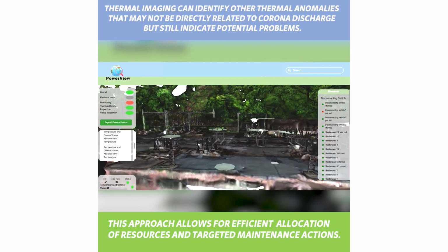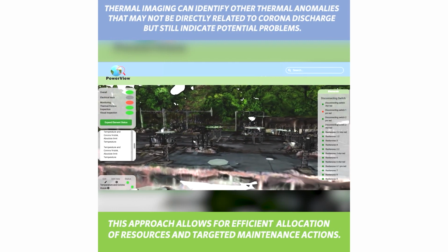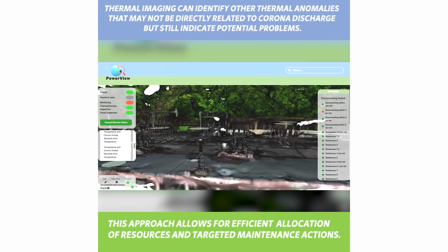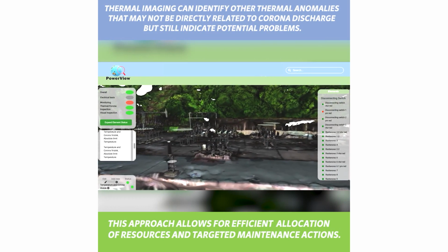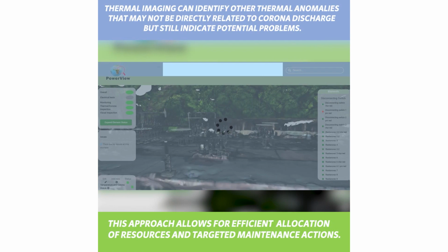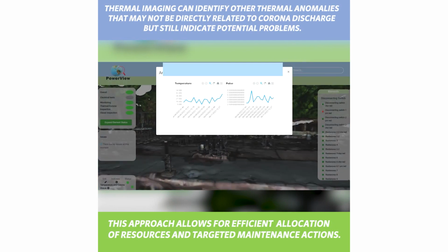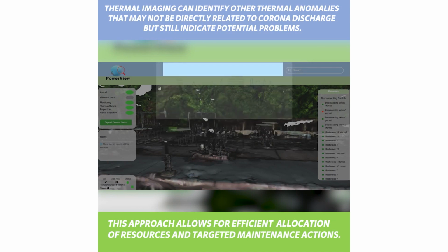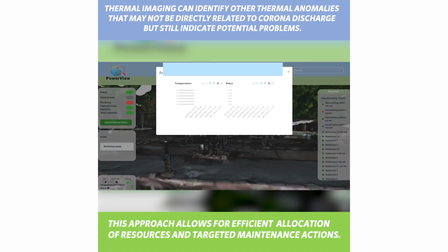The faults caused by overheating of electrical equipment or materials are mostly related to large current due to insulation failure, bad contacts, poor craftsmanship or material imperfection, etc. Corona problems are generally related to insulation's degradation, geometrical deformations, surface contamination, and low clearance.